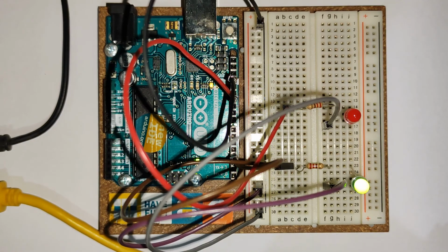So, again, let's upload it. As we can see in the behavior or reaction of the LED, it's already blinking faster because I've set the on time and off time to the same value, which is 500 milliseconds. If you want to control the other LED, based on our analysis, we cannot control two LEDs at once. Again, there is a workaround for doing this in this Arduino sketch, but it is not the scope of our tutorial.